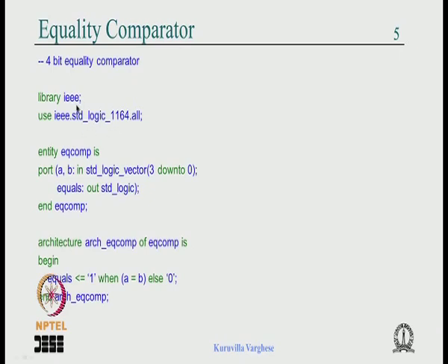Okay, so that's hierarchy, and we are going to use a particular package within this library called standard logic, std_logic_1164.all. So we are going to use this particular package for this entity and architecture, that's the meaning of this. And from now onwards we are going to use the standard logic library.